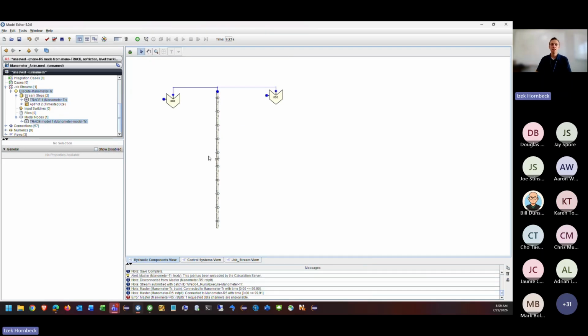Yeah, Mark, did you have something? Yeah, just a note, and I think everybody that's run RELAP5 is aware of this, that in RELAP5, when you want a dry non-condensable, RELAP5 has a flag that if you put in 0 for the quality, it recognizes that as a dry non-condensable. And so in the RELAP5 model that we just looked at, that's what the 0 is saying, not that it's a 0 non-condensable, it's just dry non-condensable.